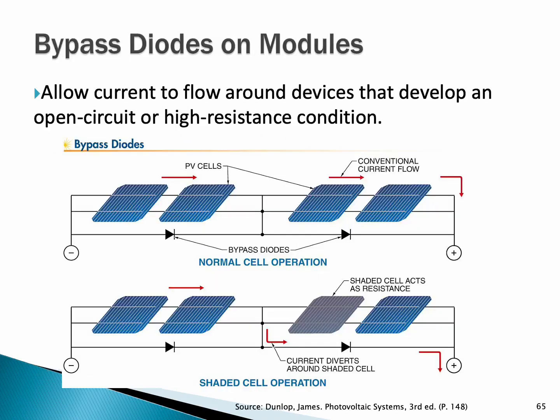I wanted to show you this. I don't think we've seen this before. This is the blocking diode concept. Here's one cell group. Here's another cell group. And then here are the blocking diodes on a possible detour route. So when things are operating normally, current is flowing from negative to positive through these wires right here, these pickups.